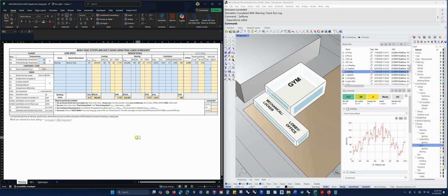But the point is, in this case, the difference between our supply air for heating and our set point is 27 degrees. So we're going to be moving a lot more heat in that air for heating than we are for cooling. That means we're going to need less air to move that amount of heat. Okay, so that means we're more efficiently using less air on the heating side than the cooling side. So we have a higher peak load, but we have a lower CFM.